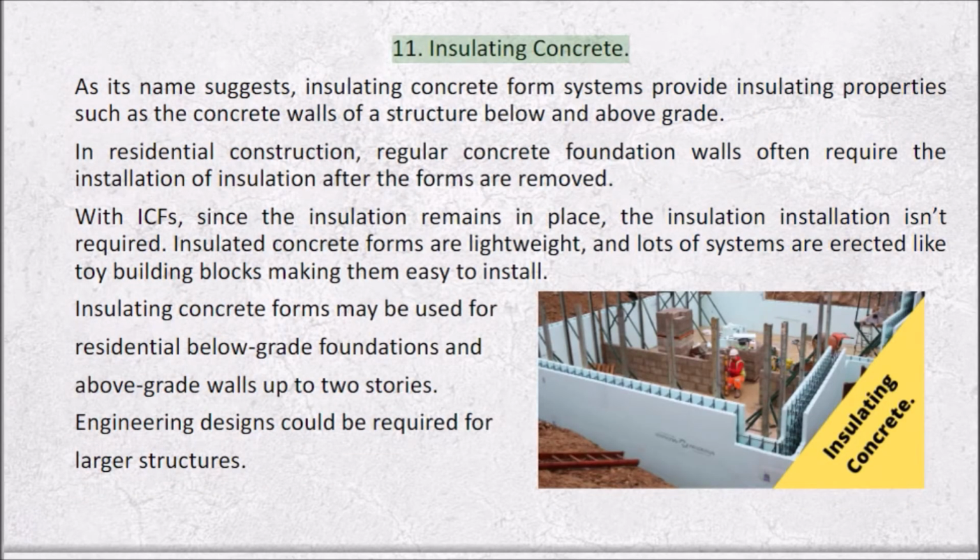11. Insulating concrete. As its name suggests, insulating concrete form systems provide insulating properties such as the concrete walls of a structure below and above grade. In residential construction, regular concrete foundation walls often require the installation of insulation after the forms are removed. With ICFs, since the insulation remains in place, the insulation installation isn't required.